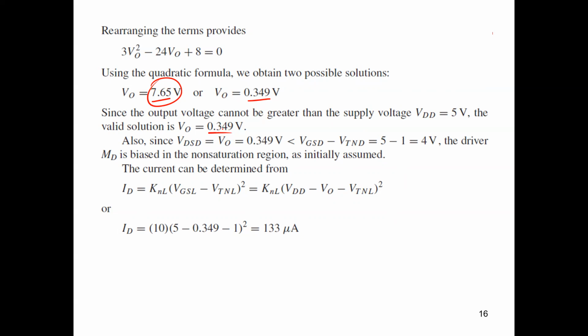So when we apply input voltage 5, we get output voltage equals 0.349, which can be considered active low. This voltage magnitude can be considered an active low signal. We have a pattern for active high and active low signals, and it can be different from one circuit or IC to another.